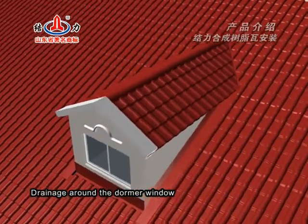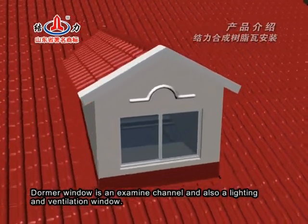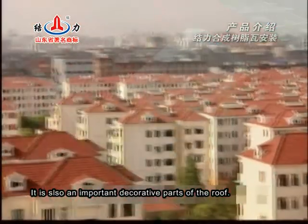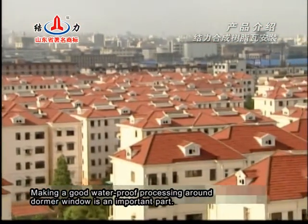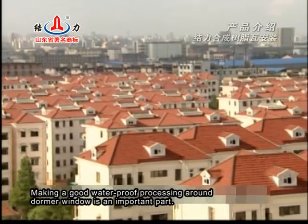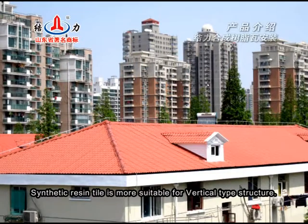Drainage around the dormer window. The dormer window is an examined channel and also a lighting and ventilation window. It is also an important decorative part of the roof. Making a good waterproof processing around the dormer window is an important part. Common structures of dormer window are vertical type and horizontal type. Synthetic resin tile is more suitable for the vertical type structure.